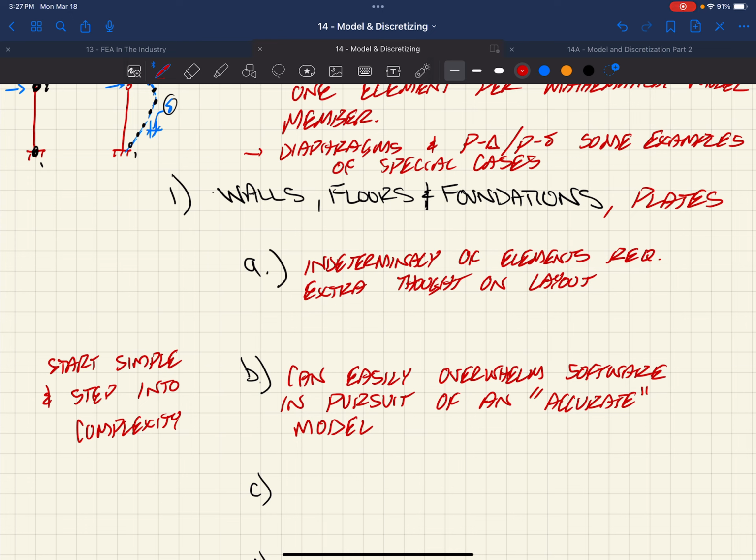and what's going on between elements. If we're going to design, say, Norm, for instance, it has all of these off angles, nothing square, it has clear stories, vertical offsets, horizontal offsets in the lateral resisting system. It's a big moment frame, which is complicated in its fully restrained moment connections. I mentioned you have to take the stiffness of those connections into account, which proprietary businesses that design such elements are able to help you do, but you have to integrate it into a model. So what do you do? You start with something very, very simple.